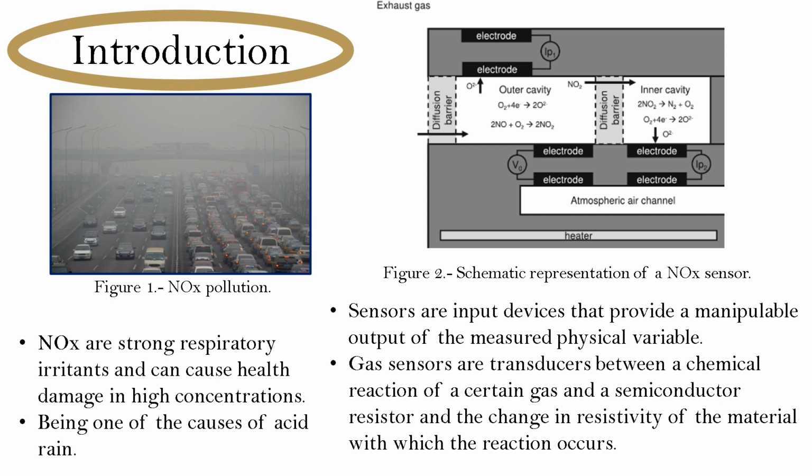This type of sensor requires careful characterization in the face of variation in temperature and relative humidity, since if the chemical reaction for which a resistance variation corresponds occurs at a different temperature, a measurement error will occur. Modern versions of NOx sensors need a filter to keep the sensor at high temperature where the device has good resolution, plus some delay to start measuring when turned on.